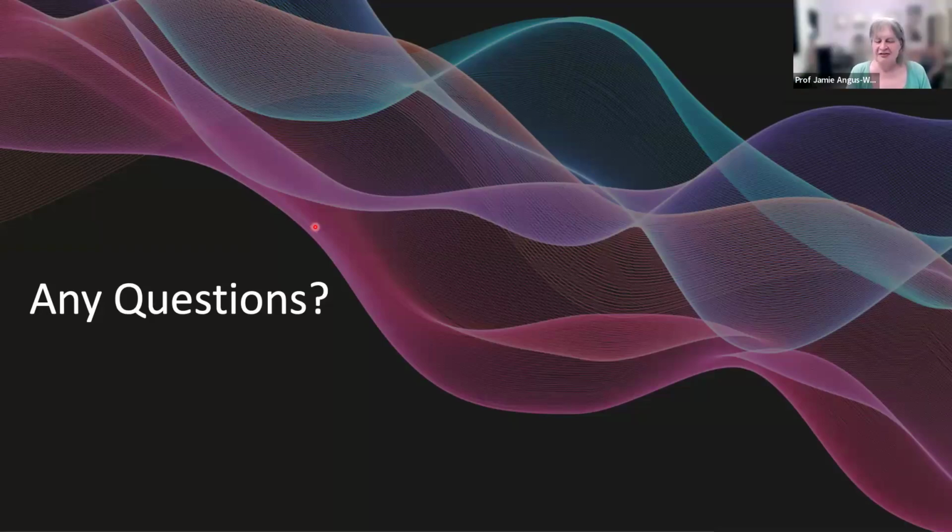Essentially, to make these nonlinear devices work, you need the waveform, all of it, not the sampled version of it. If you just apply rules to the samples of a nonlinear device, you're not going to get the same result as a continuous analog circuit. So I think there's no reason in principle, but in practice it's actually quite a bit harder than simply writing the equations out on the samples. You actually do have to have something approximating a continuous form.